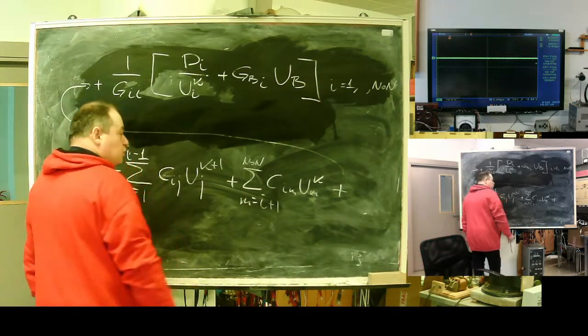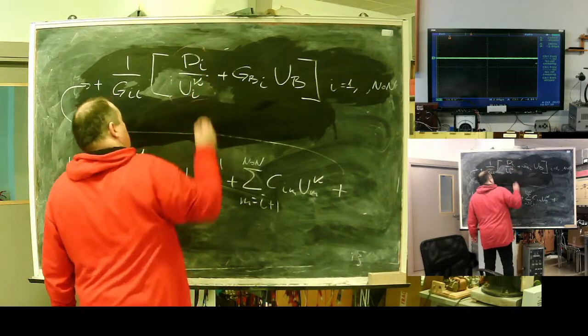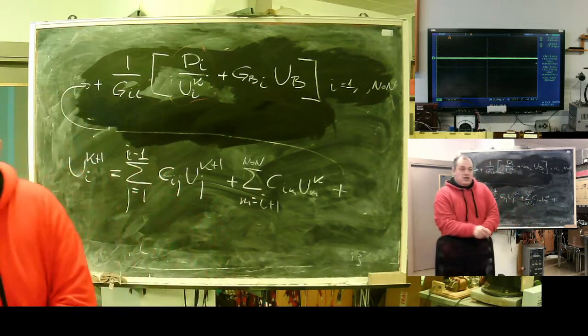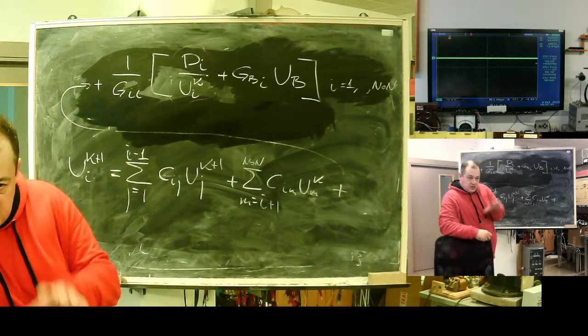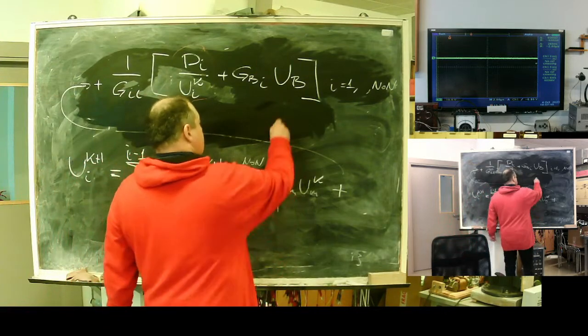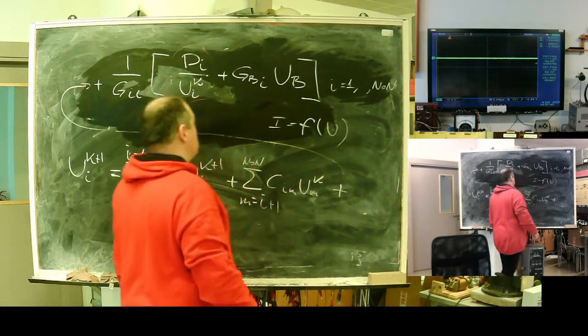It is suitable not only for constant power. Here you can plan your load or generator control strategy. You just need to set it in the form of current as a function of voltage.